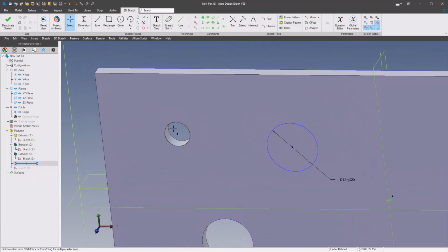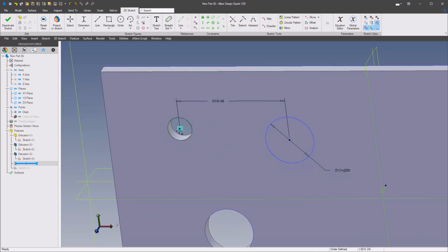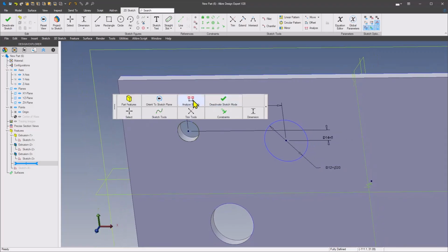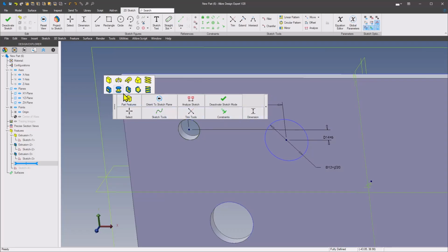That reference geometry has stayed linked to that hole, although it's been changed in size and location, it's still relative to that hole. So my dimension for this hole location here is going to be maintaining its relationship. So whatever I do here, let me cut this through here, through all.